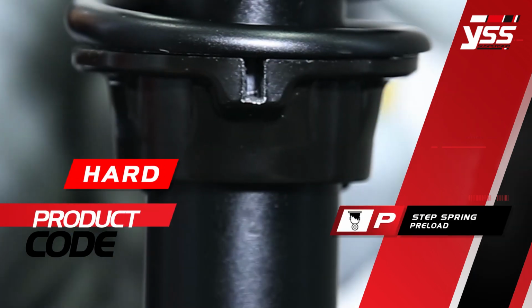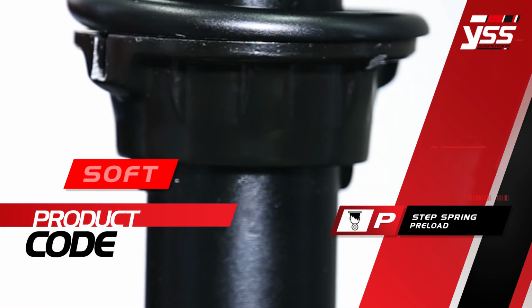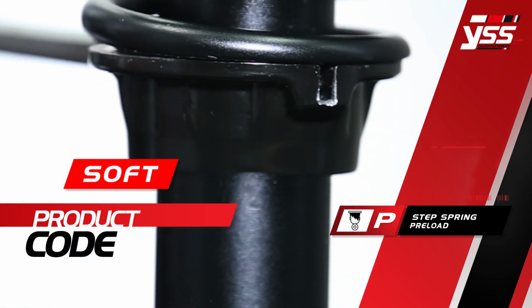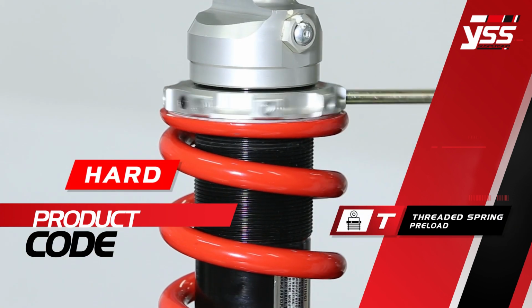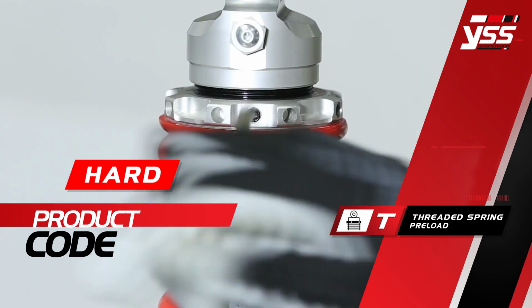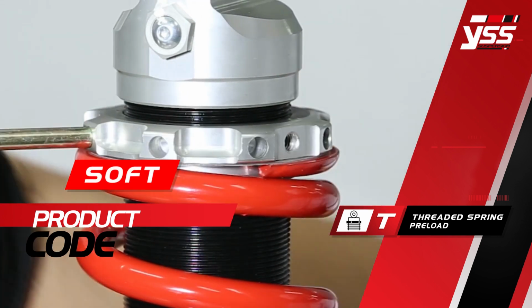P: Step spring preload is step spring adjustable. Turn to the left-hand side for harder spring. Maximum 6 to 8 steps. T: Threaded spring preload. Screw the spring preload ring to press the spring and tighten together to lock the ring at the desired position.